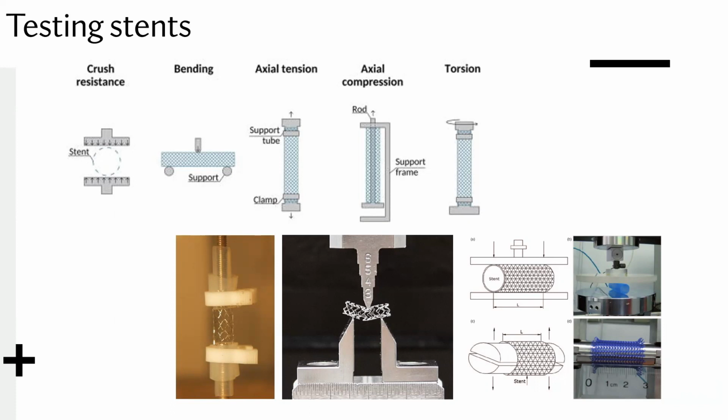One of the most important properties is the elongation. How much can you stretch the stent before it fails, because these usually get contracted during the process. They get crimped, and basically when they're deployed, they actually extend. So we want to know what those safe regimes are to reach from the elastic to the plastic regime.